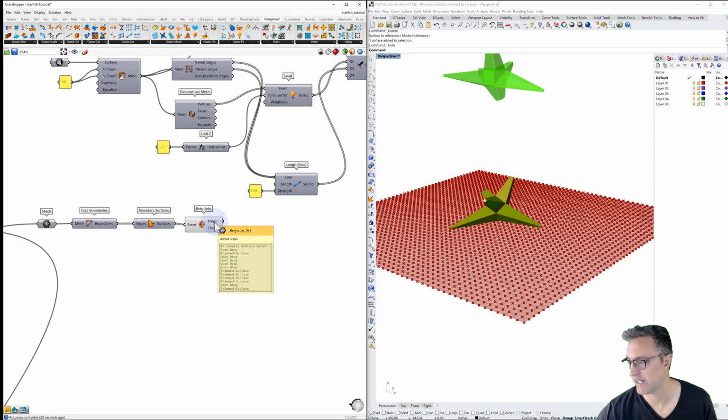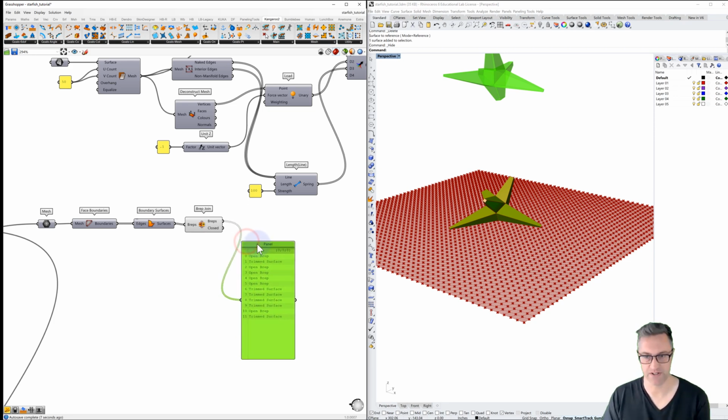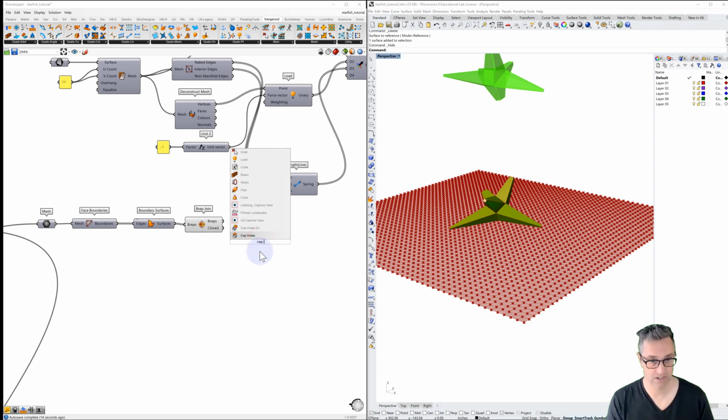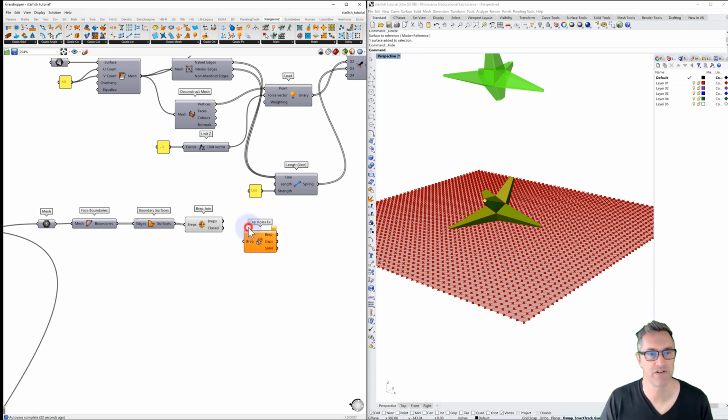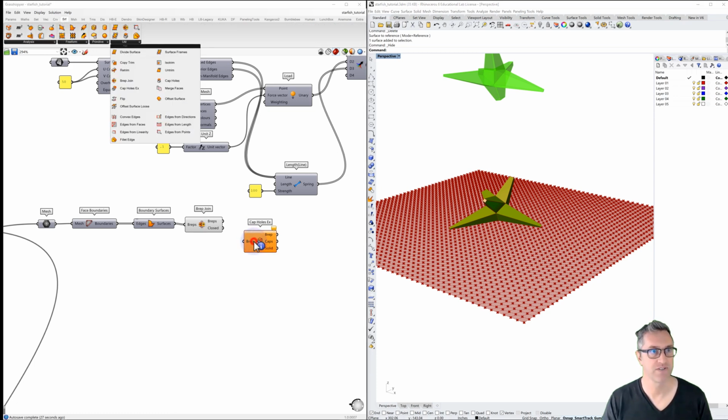And so now that we have that, let's make a quick panel. Breps coming out of this. We can see open brep, trimmed surface, open brep, trimmed surfaces. So it's a whole collection of different elements from that. Let's cap our holes. And for this, we're going to use Cap Holes Ex, cap as many holes as possible in a brep. Okay, so that's under Surfaces.